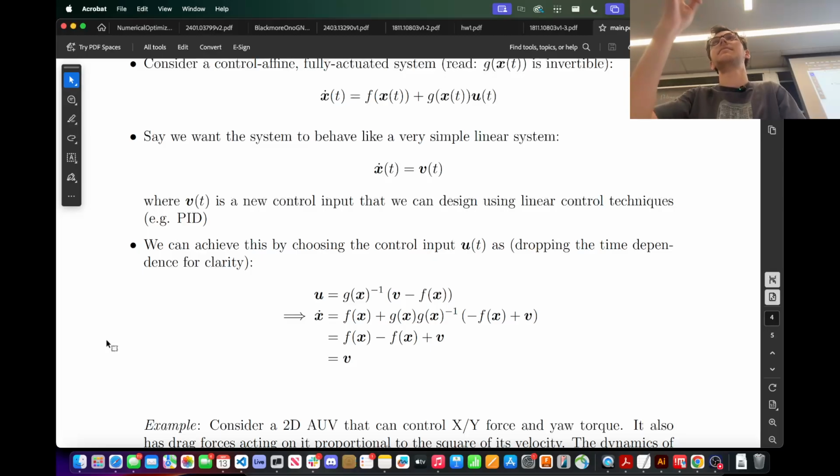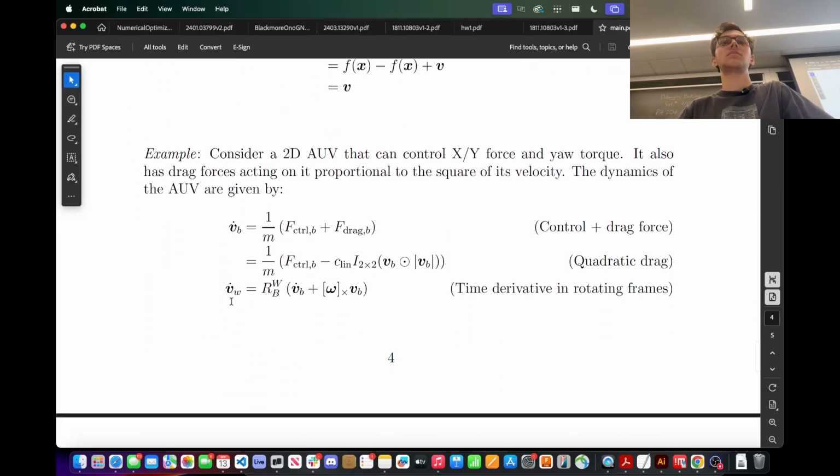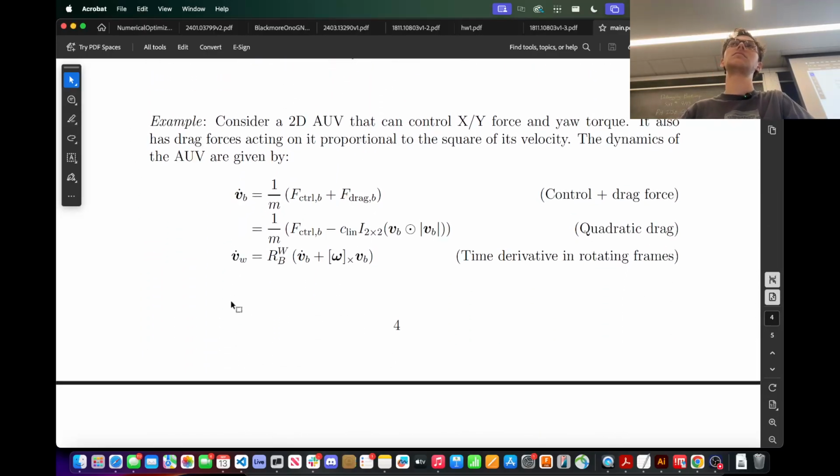What were you going to say, Gleb? Yeah, just to add to this, our suction tube right now has essentially the same thruster that we use for the sub thrusters, for the actual thruster configuration Mike was talking about, and the ninth is on the arm. We haven't tested the suction arm yet, but when we do, we're going to have thrust created by the suction thruster. The plan there is to just treat it as another thruster on the sub.